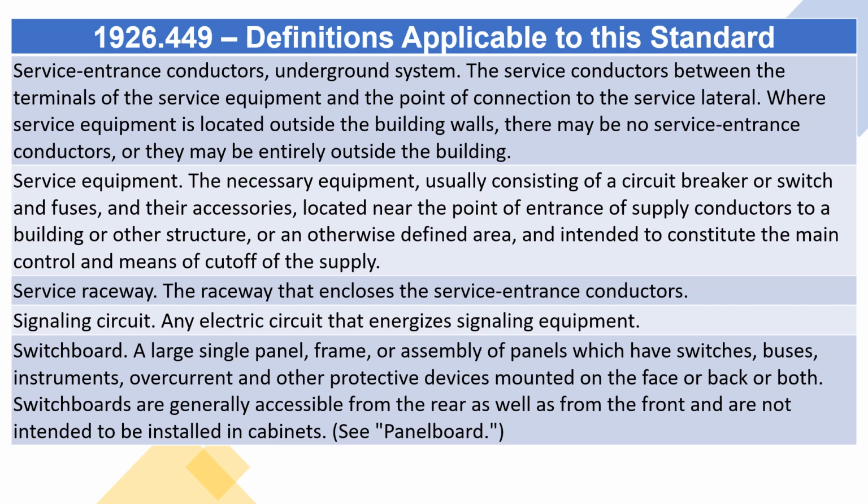Service raceway. The raceway that encloses the service entrance conductors. Signaling circuit. Any electric circuit that energizes signaling equipment. Switchboard. A large single panel, frame, or assembly of panels which have switches, buses, instruments, overcurrent and other protective devices mounted on the face or back or both. Switchboards are generally accessible from the rear as well as from the front and are not intended to be installed in cabinets. See panel board.